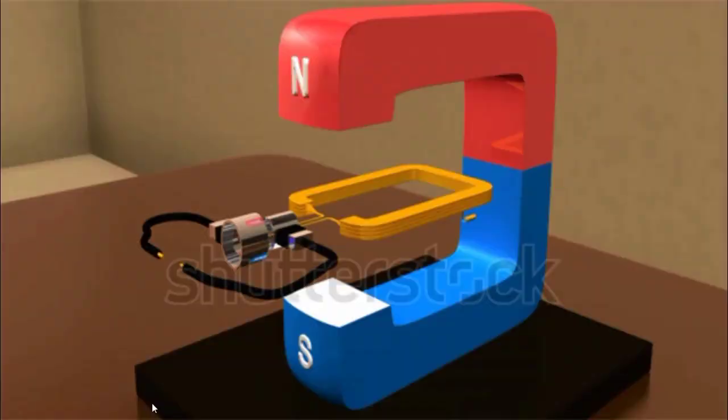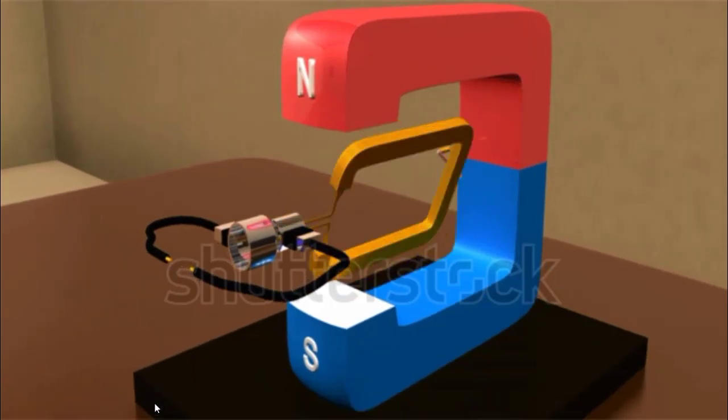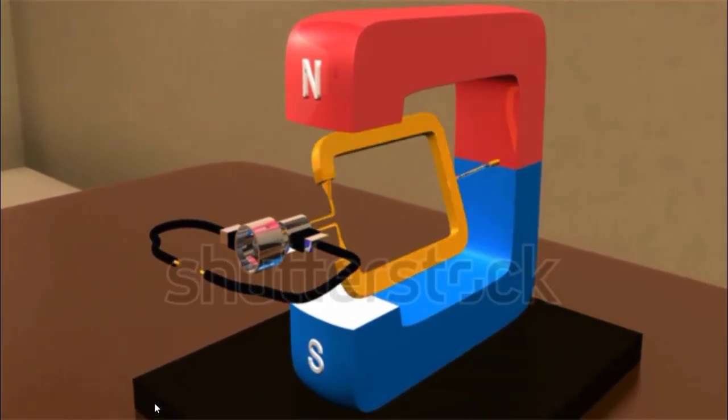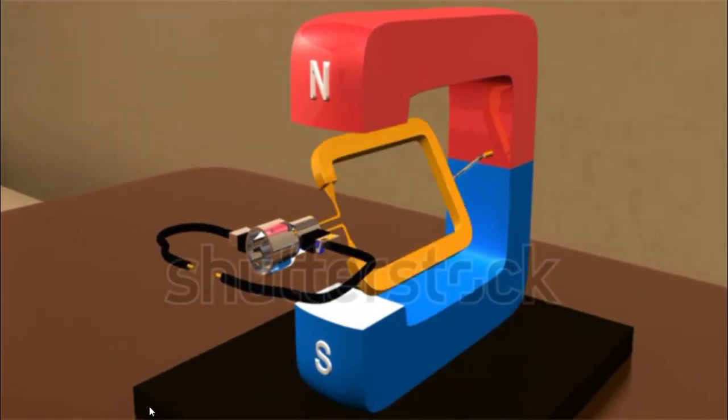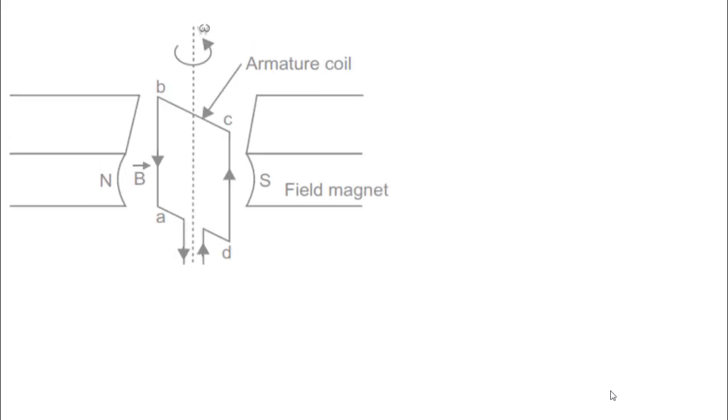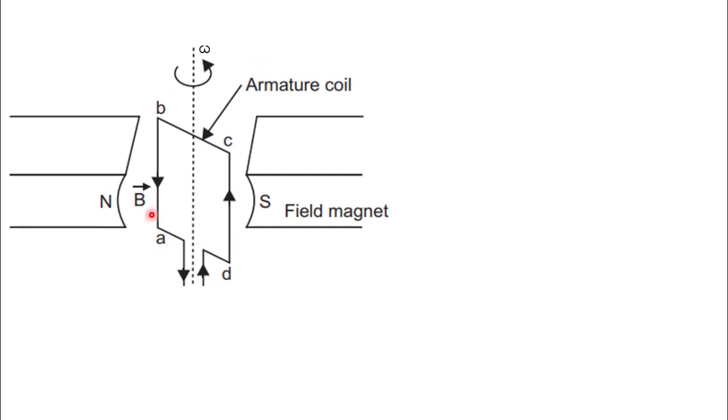In an AC generator, we choose to produce induced EMF either by rotating a conductor in the static magnetic field, or in commercial AC generators we use a static conductor called armature, around which magnets are rotated to produce an alternating current, which we shall be discussing afterwards. But to understand the working of an AC generator, we rotate the conductor inside a uniform magnetic field produced by a stationary magnet. By some source of mechanical energy, we can rotate the conductor manually by attaching a handle with it and move it inside the magnetic field provided by the magnet.